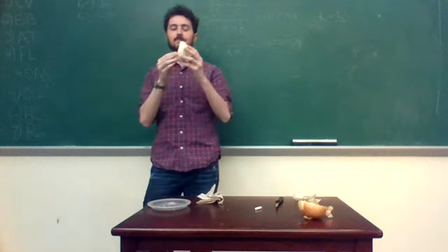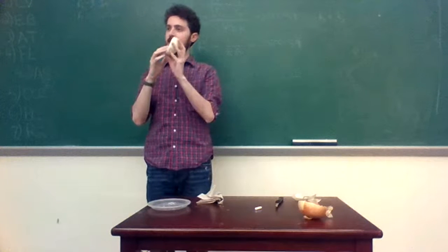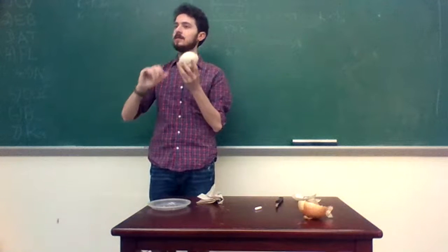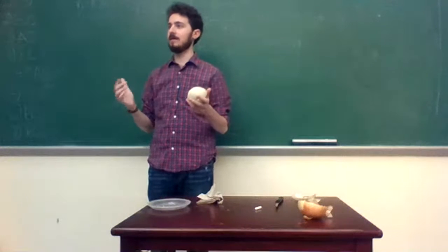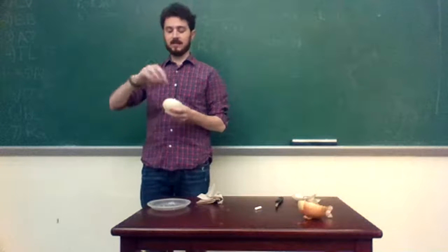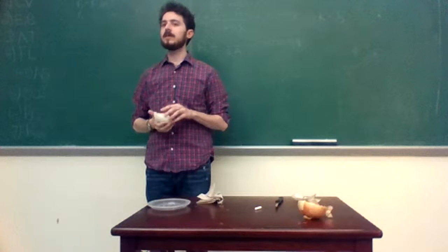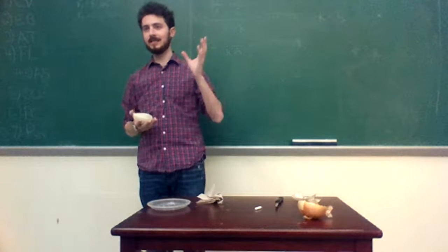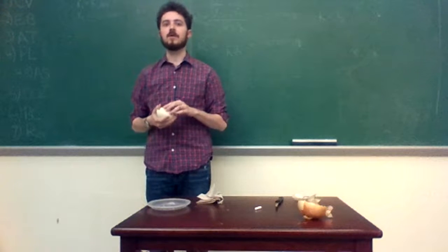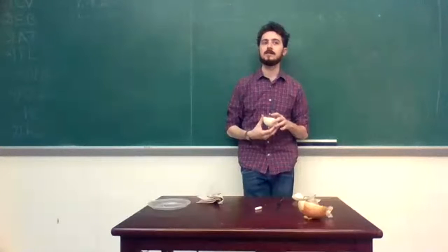When we reassemble it, we realize, okay, well, approximating this as a slab, it really starts to look less like a slab, because when you enter here, the area is very different than when you exit. So there's a real significant change in the area as you move throughout your r direction, when you've got just a very thin outer wall, and then you don't. So that's, I think, the takeaway I want you guys to have: it isn't that you should just be willy-nilly using slab approximations when you're doing spherical or cylinder problems, but that this is an extreme example, similar to the slab.